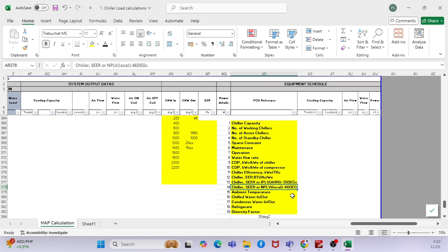When you approach the chiller manufacturer, the selection sheet already mentions it. So when it comes for approval, you have to verify what the value is. Why does the IPLV matter, or the COP? When you go with different manufacturers, they have different technology and different refrigerants, so they have different efficiency. Some manufacturers can give you 3 COP, some 3.5, some 4. If somebody is using 4, that means they have the most efficient chiller, right? Yes.